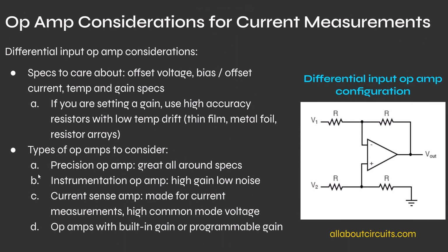All right, now that we have seen our demo, let's talk about configuring our amplifier for our shunt measurement. Now, why do we typically want to use an op amp in this setup? Well, there's multiple reasons. You get a nice high impedance. You can kind of buffer between filter stages. But the main reason is these op amps have differential inputs. And that's what we need to make sure we're just measuring the resistance of the shunt and not a single-ended measurement where we have ground plane resistance that is going to cause error in our measurement.